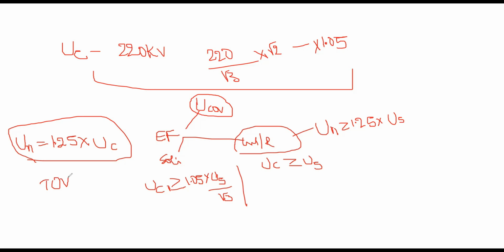We know that, so a power frequency voltage versus time characteristic will be there. That gives us the factor K suffix TOV. You can see this in the lightning arrestor characteristics in the data sheets. This is the ratio of the permissible power frequency withstand voltage to the RMS rated voltage.